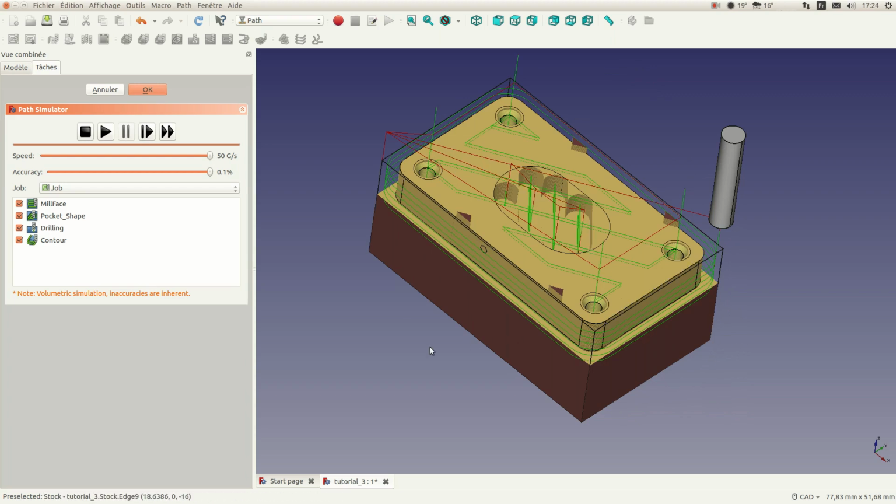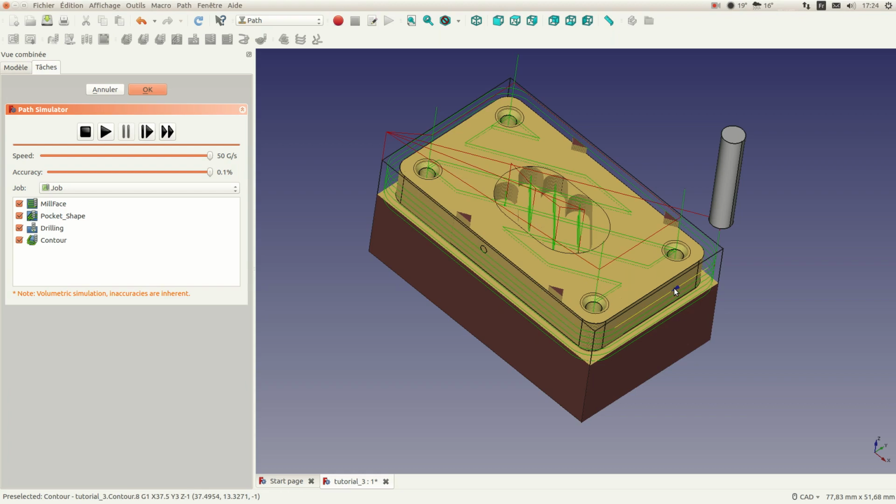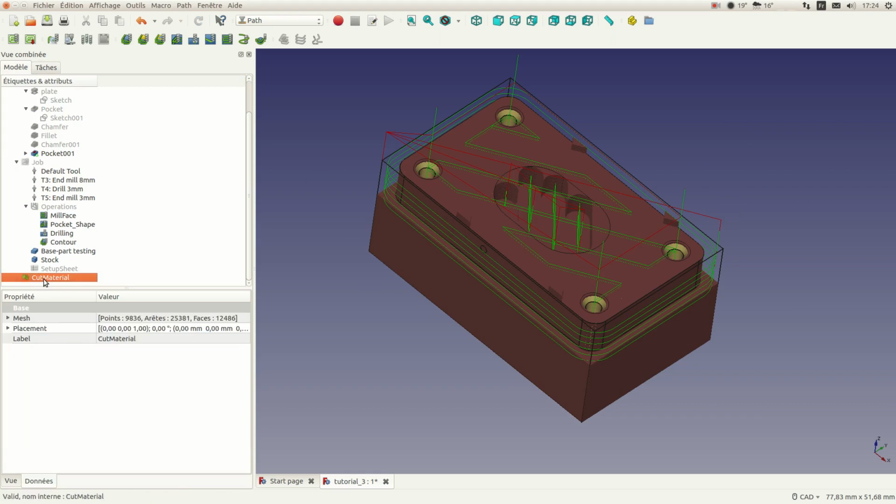And also when you have made some machining operations, you have to make some chamfering operation. For example, small chamfering around the pocket, and chamfering here also, to avoid any burrs and not to cut people. So here it is, with the path operation.